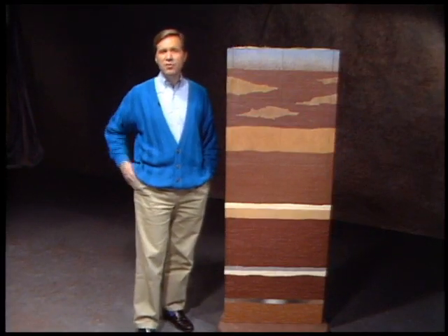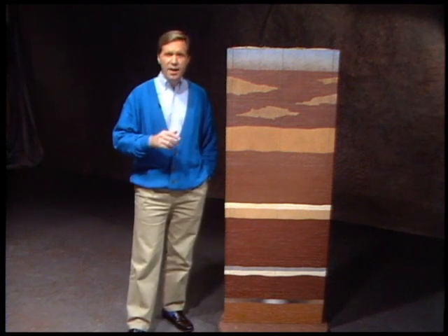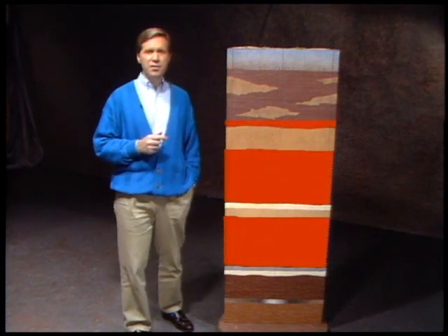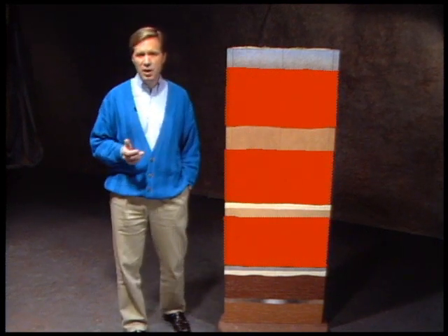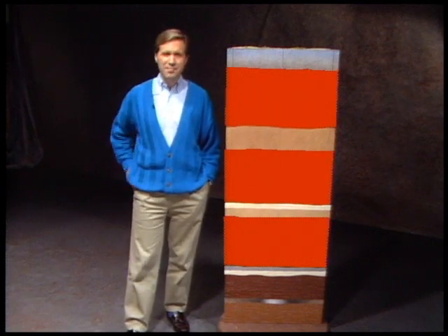Well, now we've covered the control of injected fluid as it passes through the injection wellhead and tubing and enters the injection zone. Are there any other potential pathways allowing saltwater migration from the injection zone into an underground source of drinking water? Well, to answer this question, let's look at the sequence of deposition in oil-producing areas. We typically find several layers of impermeable shale deposited between the injection zone and the freshwater sands near the surface. These layers provide additional barriers to the migration of produced water.